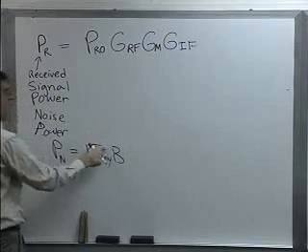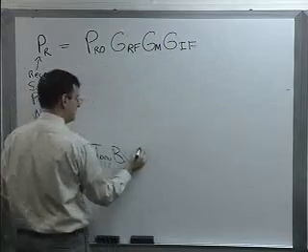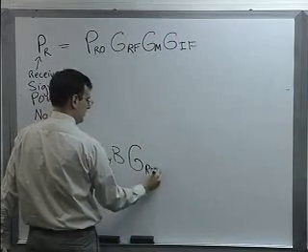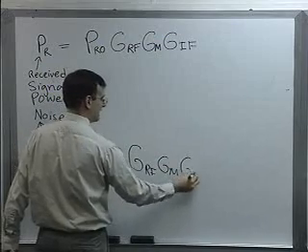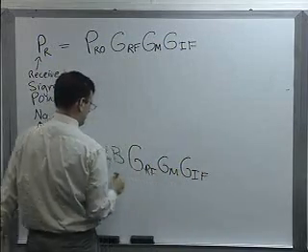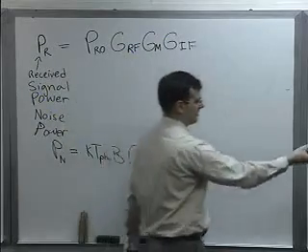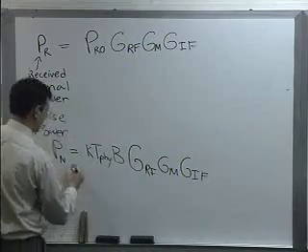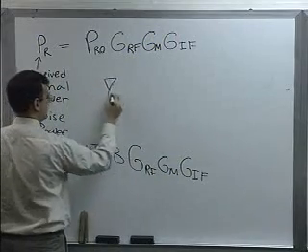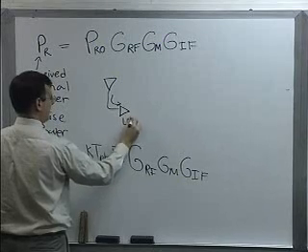And of course, that is at the very front of the system, so that's going to go through the exact same set of gains that our desired signal sees, because it's going to go through the exact same devices. After the first antenna, we're going to go through that low noise amplifier.